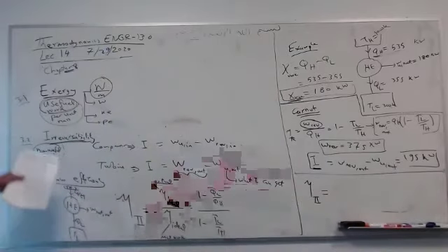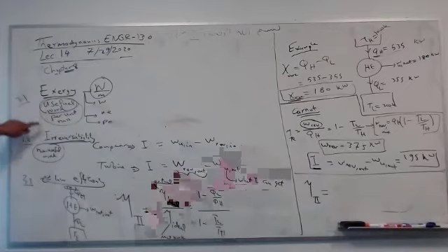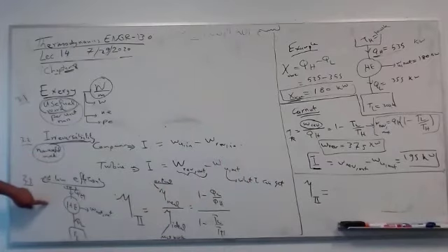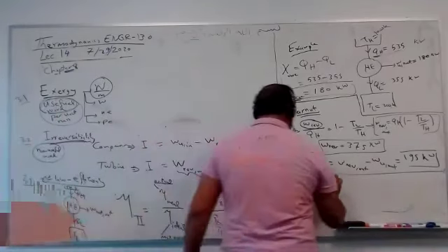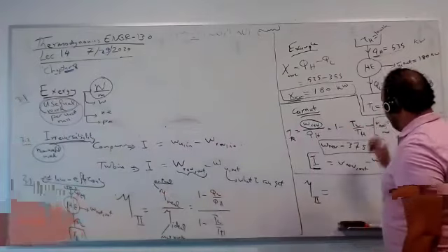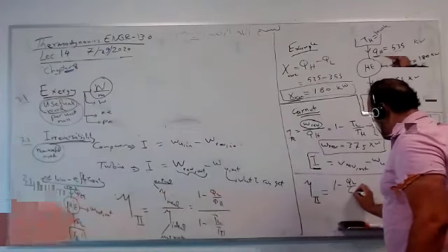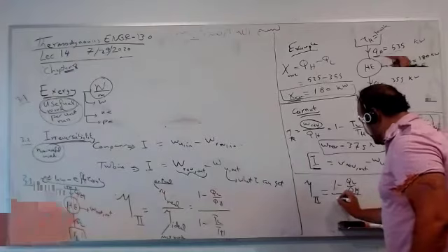How about eta second law, the second law efficiency? We get the exergy, the irreversibility, how much is useful, how much is non-useful: the ratio between two efficiencies, real to ideal, of course lower than 1. Every efficiency is lower than 1, of course. If you find an efficiency greater than 1, it means you did something wrong. So real over ideal. Ideal is much more efficient, of course. Because we have Q low and Q high, it's much better to say Q low, Q high.